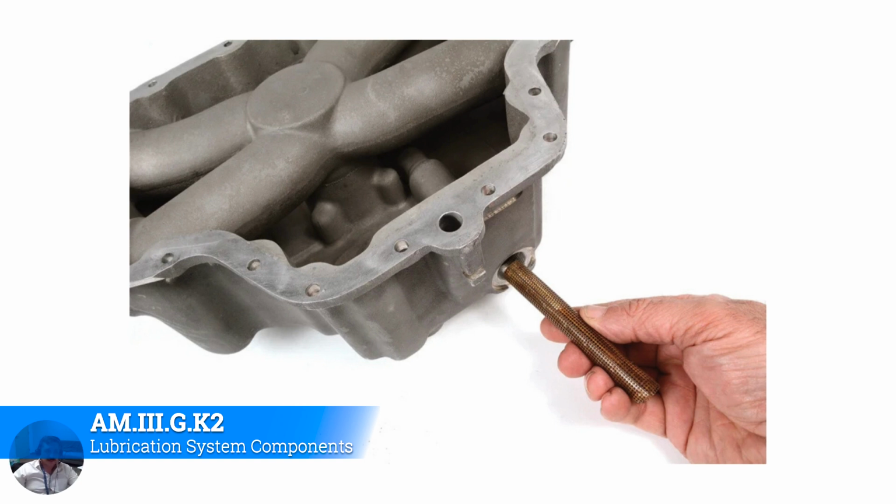You'll see little bits of carbon and blackness and dirt and stuff like that, and you just blow those out. The main thing that is really a cause of concern is if you find metal in there. You hear people talk about making metal, but this is part of just the engine or the oil filtration system. You want it to be nice and clean. That's always part of your oil changes.